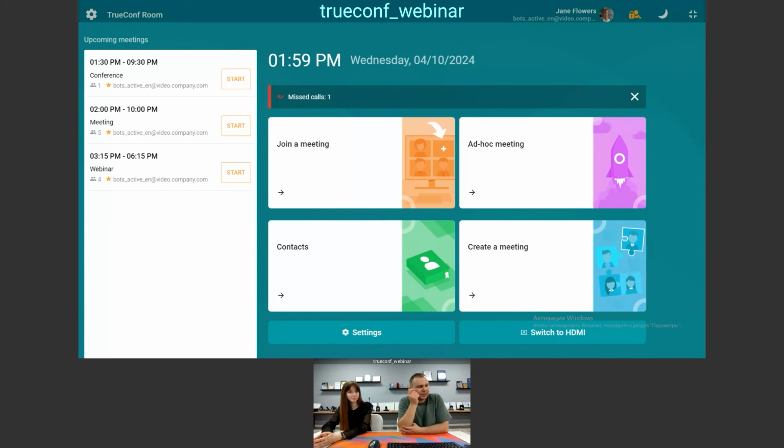And Visca protocol is much quicker and much more responsive than the USB, because when we use the USB way to control cameras, which is called UVC protocol, it is always sluggish. UVC is definitely not the best way to control PTZ cameras, but with Visca, you can do it smoothly, lightly, very quickly, without the feedback, without any delay.